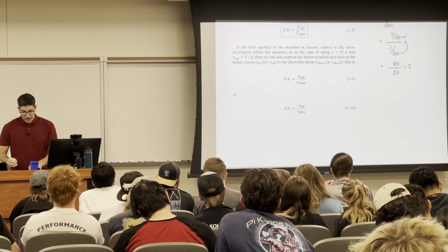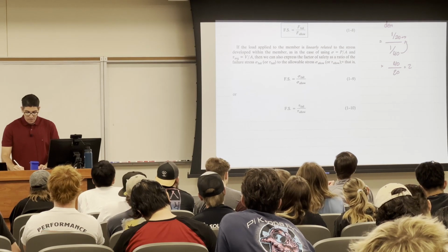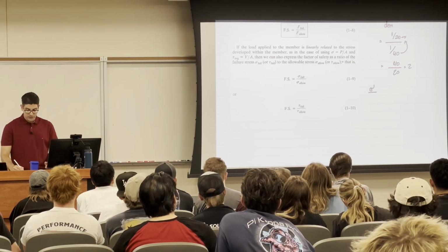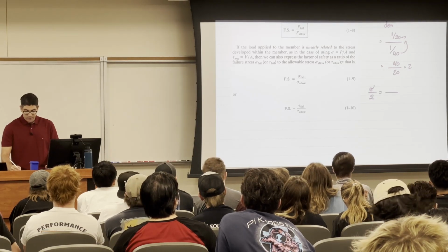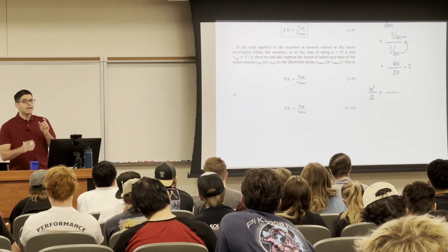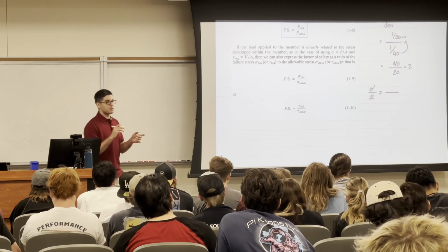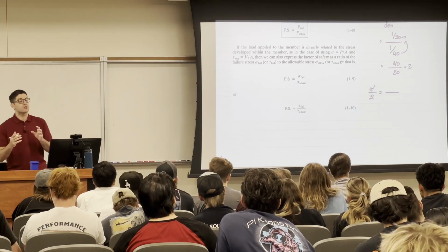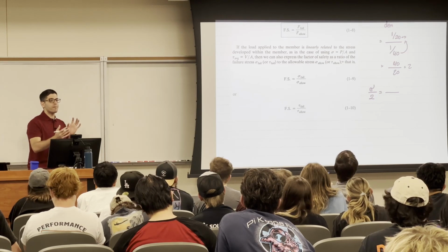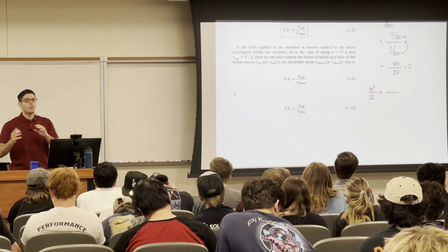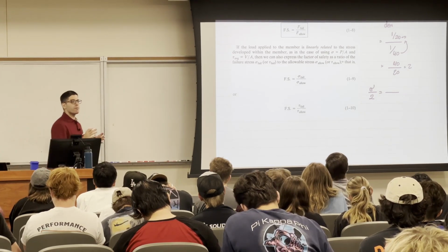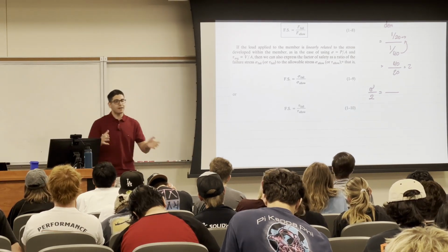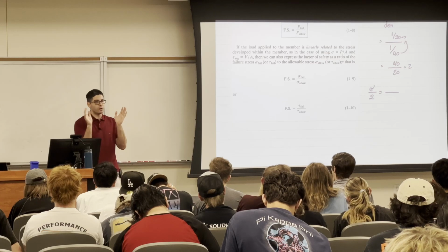And another thing is, if I want to apply a factor of safety of 2, you can either divide the stress by 2 or multiply the whole area by 2, because I was mistaken in saying multiply the diameter by 2, but no, multiply the whole area by 2. Sometimes we need the area, and after we have the area, we worry about what shape the column looks like, whether circular, rectangle, or square, but at least we have the area, and we can't go below it.